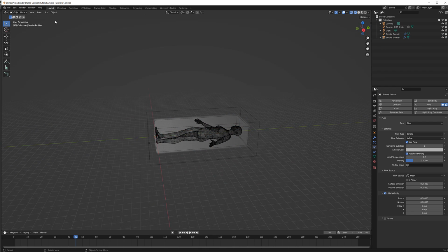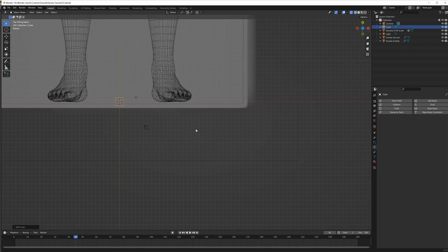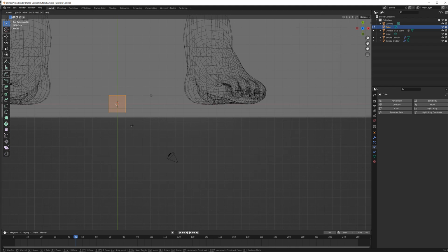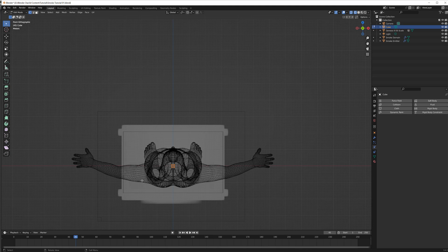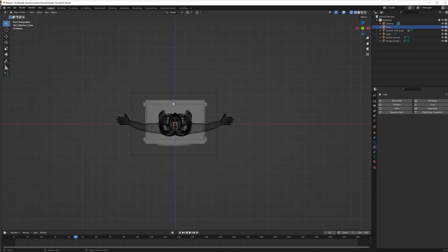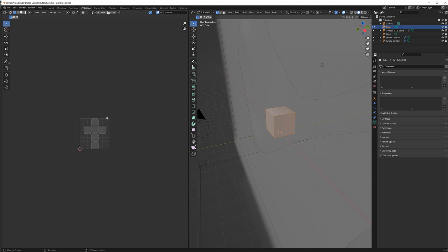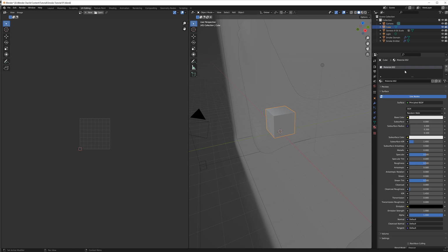So in Blender, I'm going to do add mesh and cube again, and this time I'm just going to leave it very tiny. I'm going to hit tab and move it on the z-axis so that its center is at the bottom of the cube, and hit Control A, all transforms. It should already have a simple UV map that's adequate because no one's going to see this object in the scene. And I'll just leave it with a basic material called, I think it has to be called volume for it to work. So I'm going to call that volume.